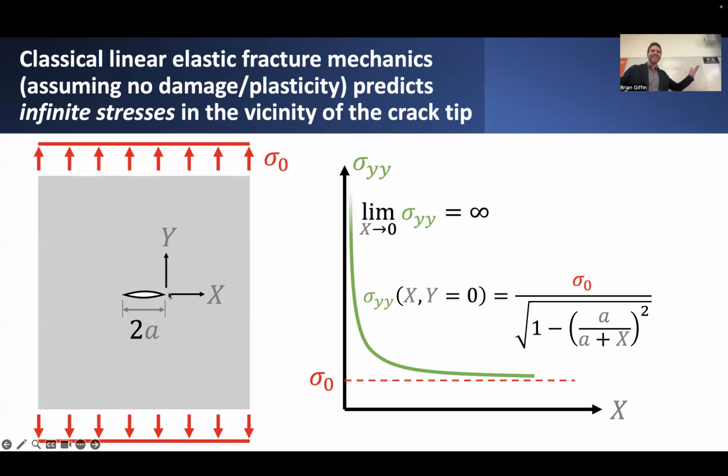And the only way to assess that is, again, to define something that understands how much plasticity has occurred, or in other words, how much energy has been dissipated in this localized zone ahead of the crack tip, sufficient to advance the actual crack. So again, this further reinforces the idea that the proper way to define a criterion for fracture is in terms of some energetic criterion.